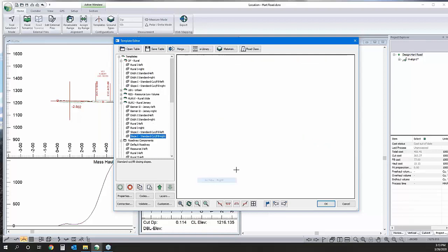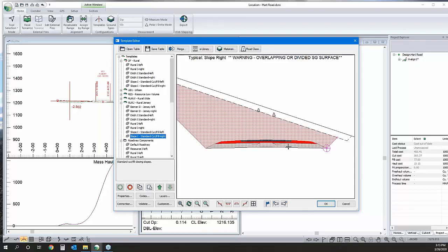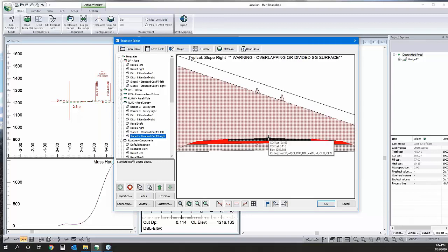So this doesn't look very right, and there's a reason for that. So first of all, we've got our Jersey barrier sitting up on top of our strip topo surface, and we've got our ditch attached to our center line. So the reason for that is there's a construction order as far as the software is concerned. So when it's building the different components, it's starting from the top down in the list. So it's building the Jersey barriers.